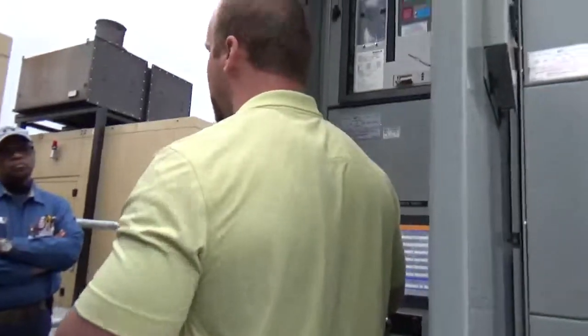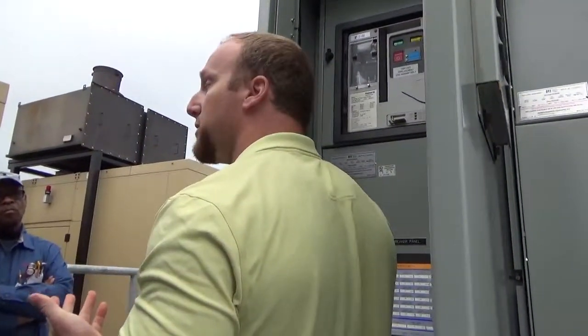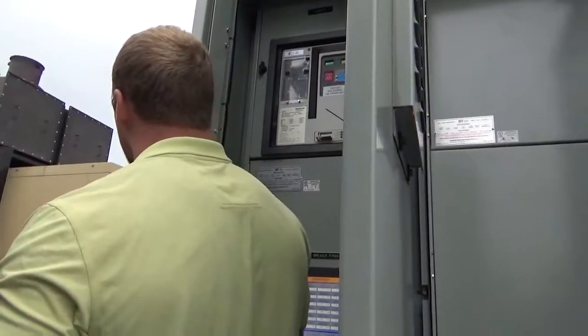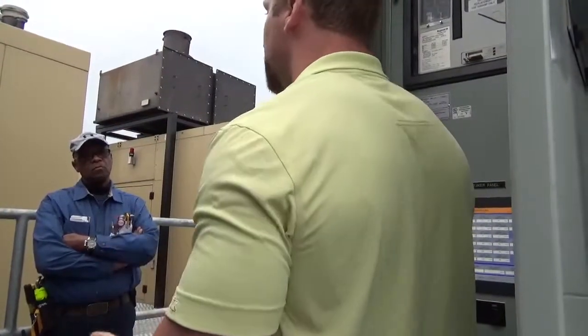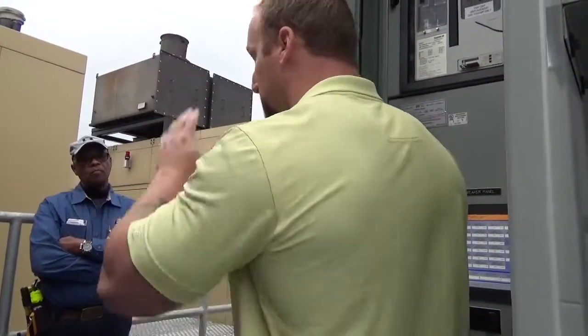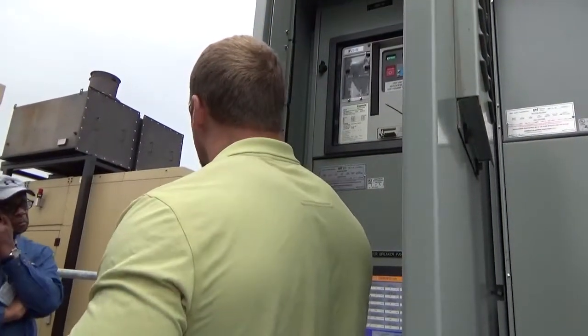And it shuts it down after so many, I'll look in the settings, but normally it's about a 5-minute sensing period. It senses for 5 minutes and says, okay, I'm going to shut down. And you can prioritize which one is priority 1 or which one's priority 2. So say for instance, one time Gen 2 is priority 1, so it's going to shut down Gen 1. Gen 1 goes into a standby scenario and just sits there.